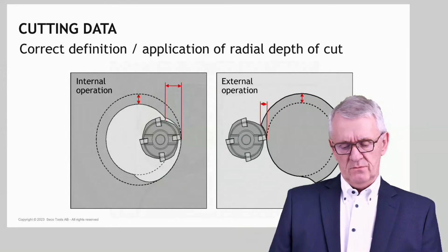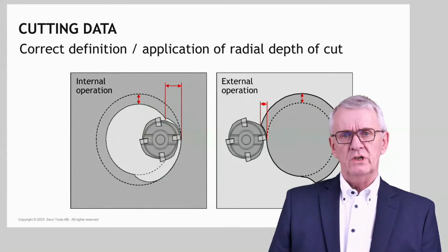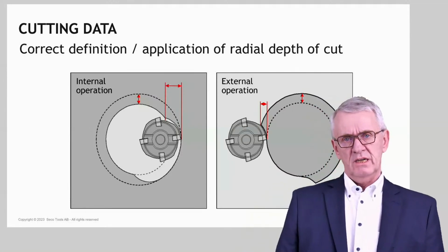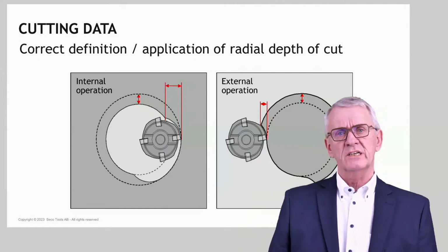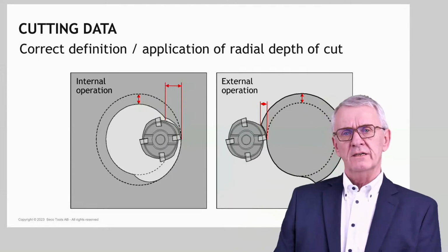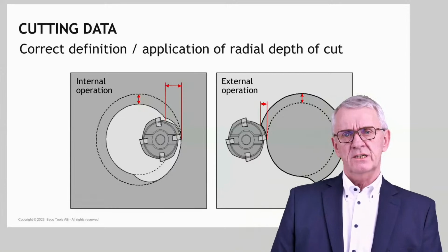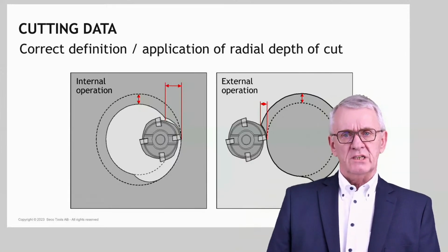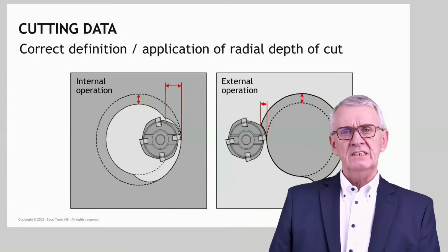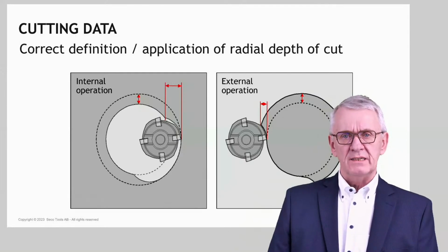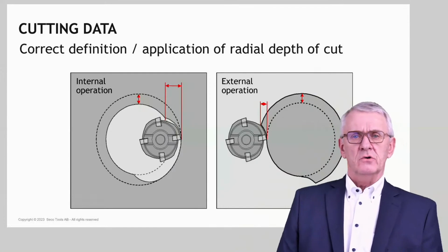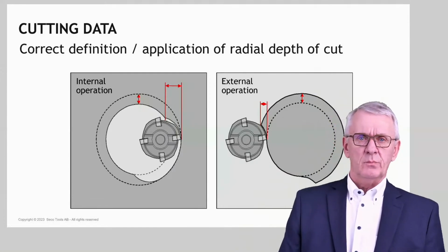It's also, when we look at the type of milling, if we do linear milling or non-linear milling as an operation, linear milling means that the center of the milling cutter is following a straight line over or in a workpiece. We refer to that as linear milling. If we do non-linear milling, and you see here two examples which are the easiest non-linear milling situations, it's circular milling.